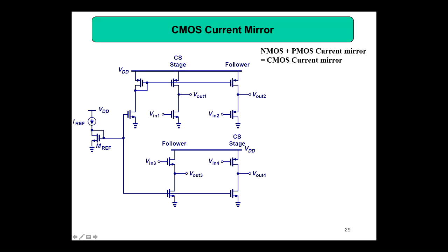So you can connect maybe 2-3 transistors in parallel, maybe 2 transistors in parallel. Here you can include maybe 1 or 2. Again, here you can connect 2 transistors or 3 transistors. Here you can connect 3 transistors or 4 transistors, depending upon the current requirement. So here you will be mirroring that current, and depending upon how many you put in here, you can match your requirement.